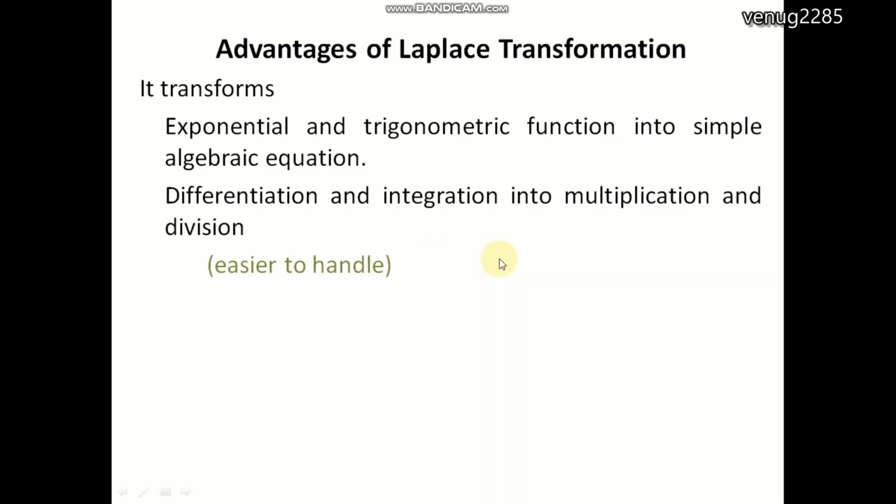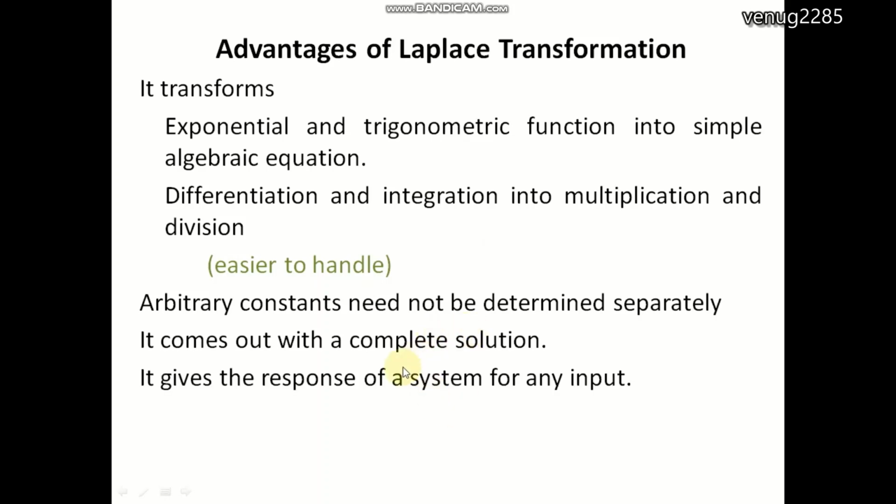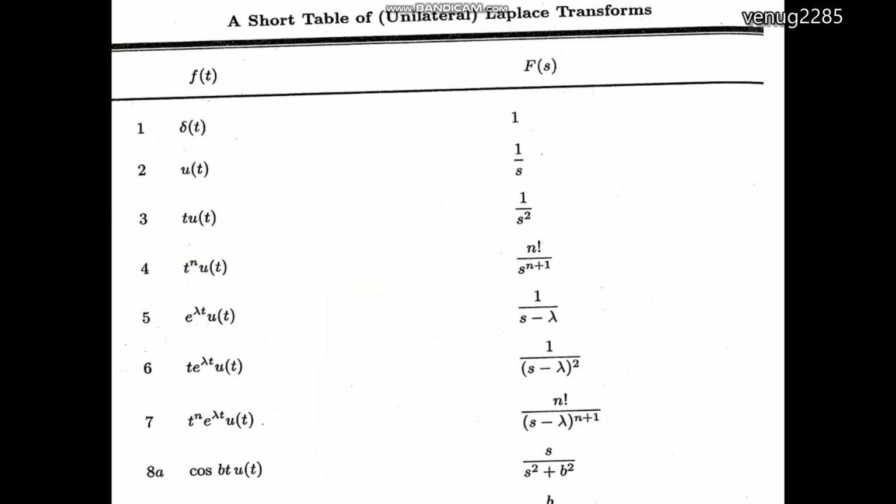It doesn't need any arbitrary constants, but in the general voltage equation, we have to specify the previously charged value of a capacitor or an inductor, and it comes out with a complete solution. And at last, it gives the response of the system for any input. It may be a step input, a ramp input, a parabolic input or an impulse input.